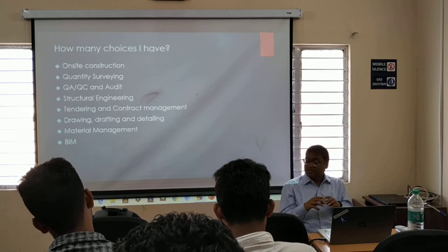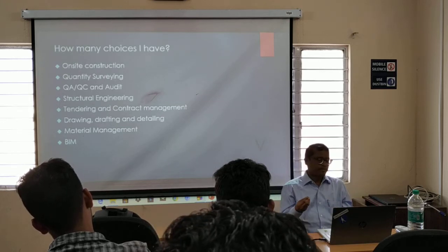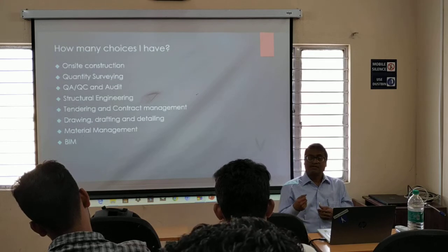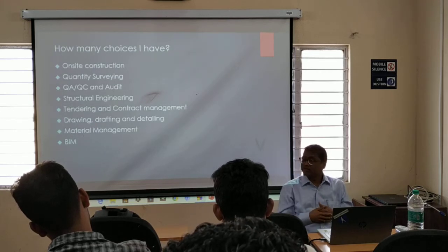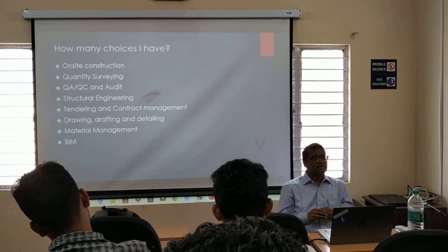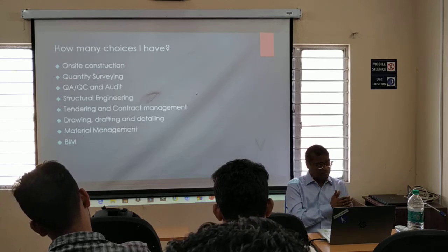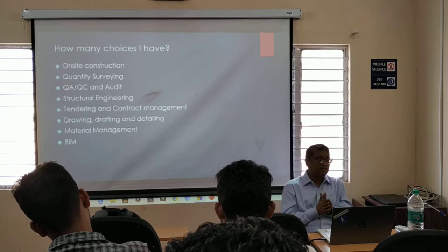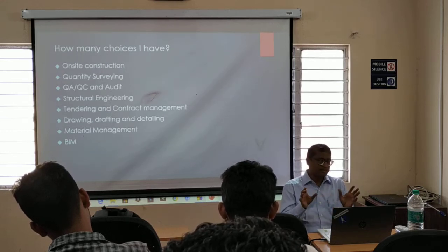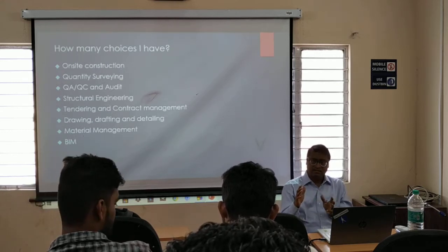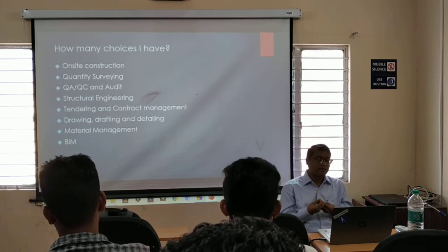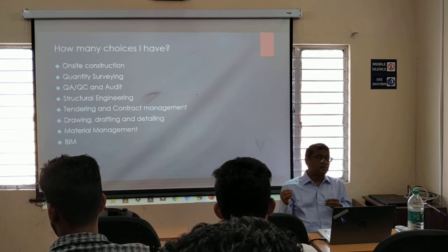Level of development is about 100, 200, 300, 400, 500 also is there. LOD 100 is only the concept drawing. 200 is only the schematic drawing. 300 is up to GFC drawing. 400 is the shop drawing. And 500 is the as-built drawing, which the maintenance team is going to use.